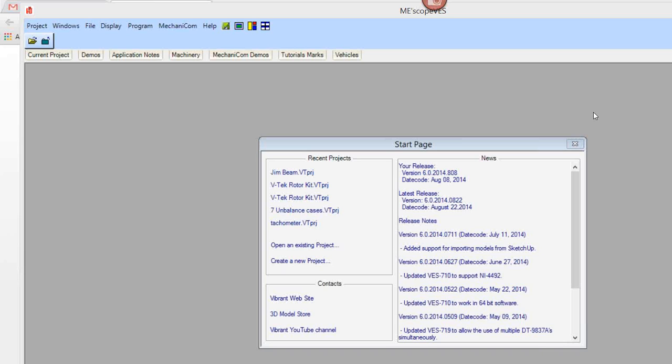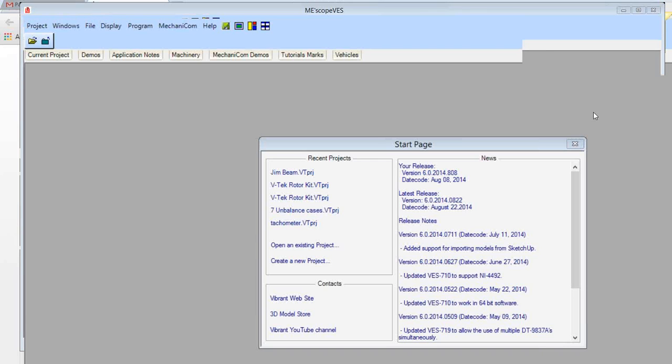And that's a hybrid measurement where we take the autospectrum of each roving response and we combine that with the phase of the cross-spectrum between that roving response and the reference. So we take the phase off the cross-spectrum, we take the autospectrum, and we marry them together in something we call an ODS-FRF. Now, those measurements are a little different than the cross-spectrum directly. Either one of those types of measurements can be curve fit to recover what we call the operating mode shapes.